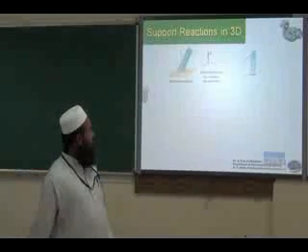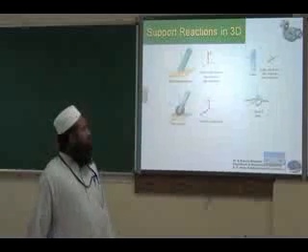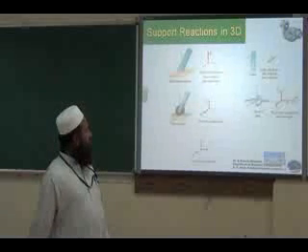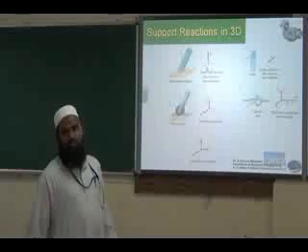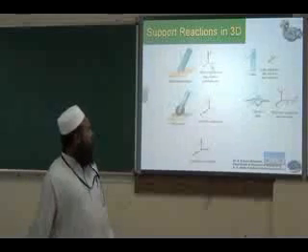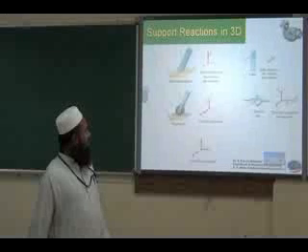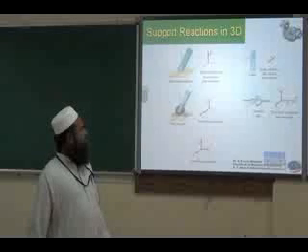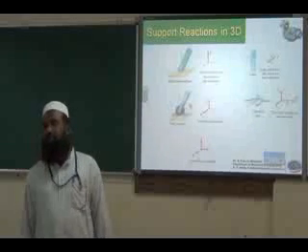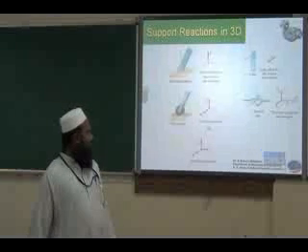So we already started with the different types of reactions. How many reactions we will have? The first case, we have a frictionless smooth surface. If it is a smooth surface, only one reaction. If it is like this, a wheel on roller, it can translate in y direction only. It cannot translate in x direction, it cannot translate in z direction. So it will have two forces.